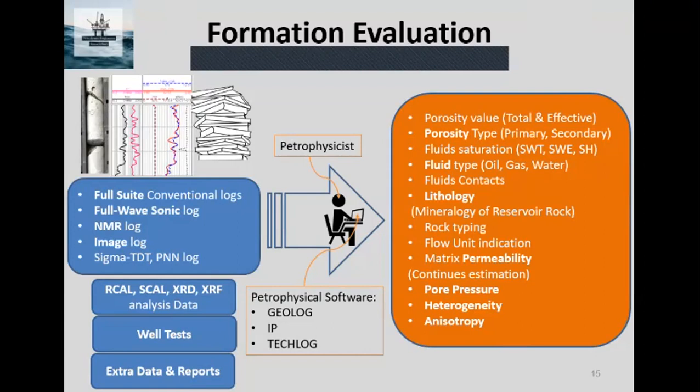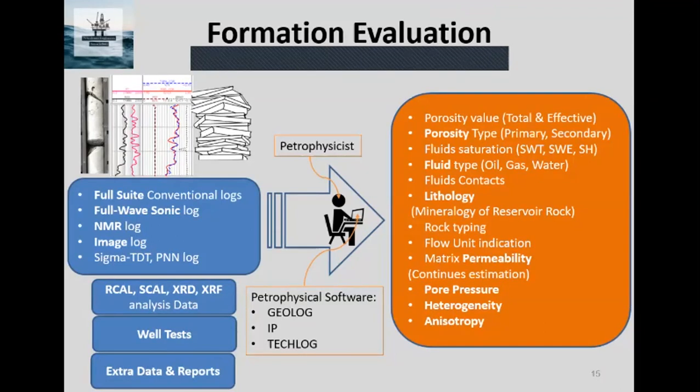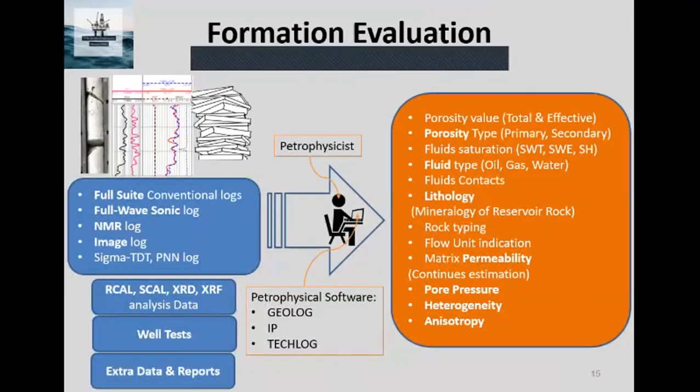In all situations, you should work accurately with the software that you have, and gain the porosity value, porosity type, fluid saturation, fluid type, fluid contact, lithology, rock typing, flow unit indication, matrix permeability as a log, not point, pore pressure, heterogeneity, anisotropy.